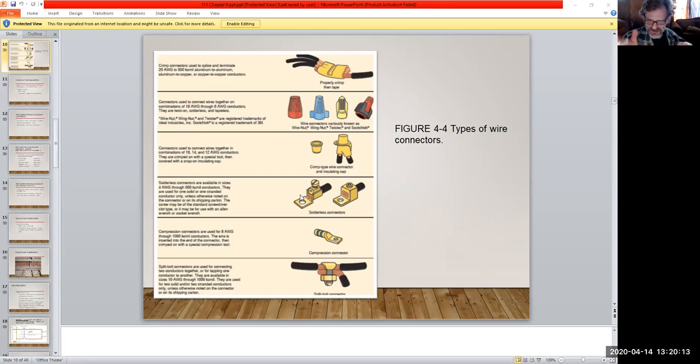The reason being is these are twist-on, right? So let's say you have these in a junction box, but somebody might not go in there for 10 to 20 years. Who knows what, the house settles, wind, this and that, you get vibrations and whatnot. And 10 to 20 years is quite some time. These can eventually back off, where they would slightly untwist. So it's a good rule to go on the very bottom of these things and give it a loop and a half to 2 loops of electrical tape just to hold it.